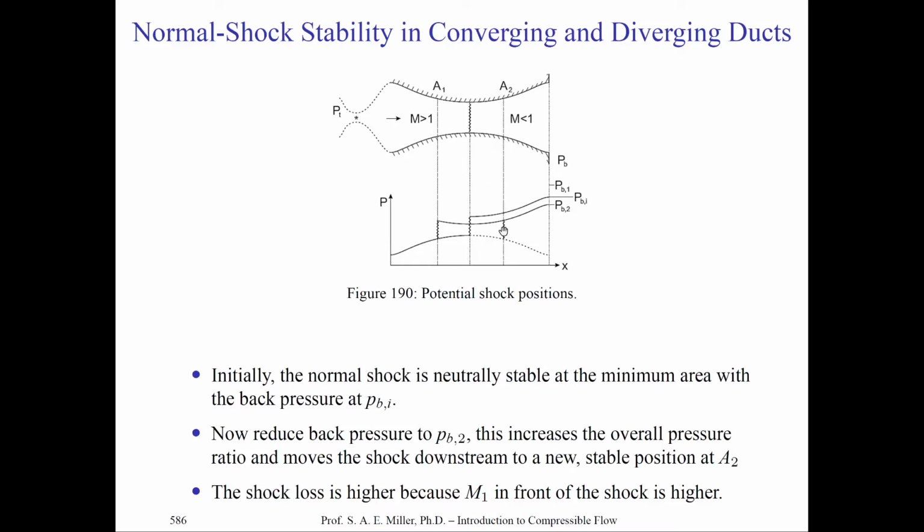So you can imagine in this case, where my cursor is moving, if you're in the divergent part of the diffuser, the shock wave is here, the Mach number is higher because we've accelerated from the transonic condition to a higher Mach number. If the shock is closer to the throat, of course, it has a lower Mach number than upstream. And you would, of course, have less entropy rise and more pressure recovery. So the shock position is really determined by the area ratios and the back pressure.